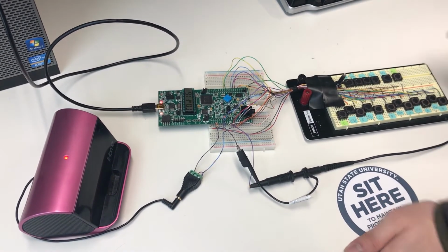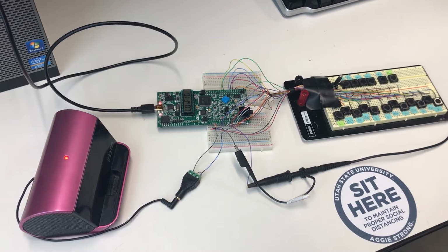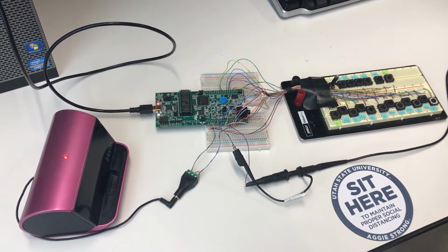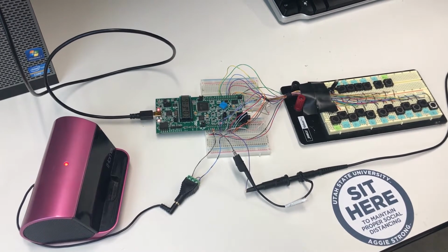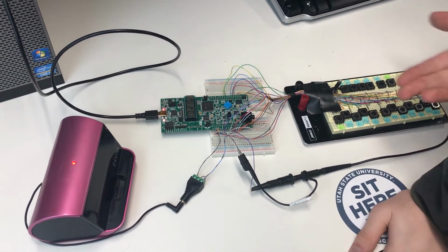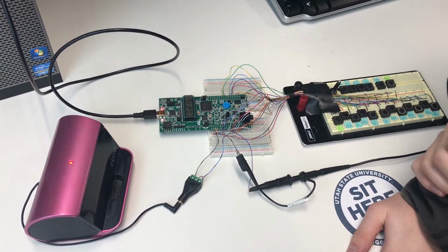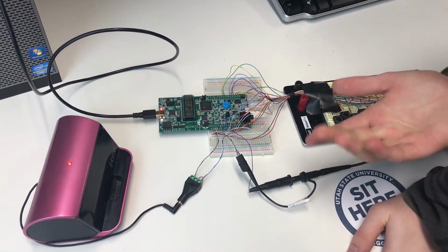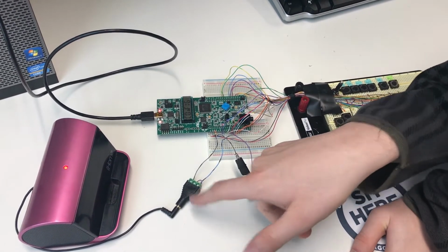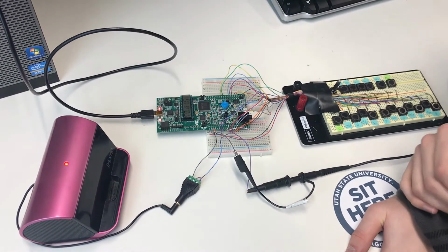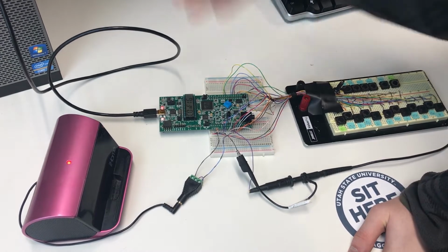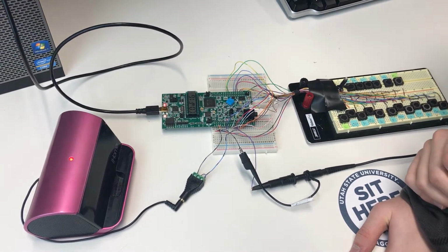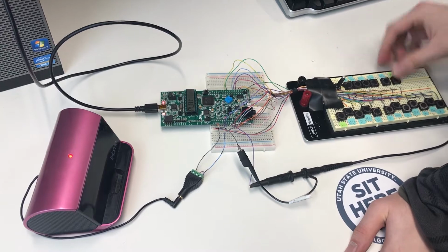However, because the serial audio interface is primarily designed to use direct memory access, and our synthesizer doesn't play from a file, it generates its own waveform, we felt it would be better to not deal with the serial audio interface. And so as you can see, we are instead using a DAC to interface with a simple female audio jack that is plugged into a GPIO port on the board. That can be plugged into any speaker or headphone system, and it will play music, as you can hear.